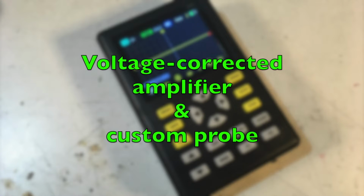Plus, you don't have the little selection reticles to go and measure the exact amplitudes and wavelengths of particular parts of the signal, which is really annoying, and that's present in a lot of these DSOs, so you don't get that here. But if I were to set this up as a fixture just for measuring noise, then I would probably build a custom voltage corrected amplifier, shooting known amplitude voltages to the front end and then readjusting, probably a JFET amplifier up at the front, or maybe feed a JFET into a MOS or an op amp, and then program the gain so that I know exactly what it's supposed to be, and then make up a custom probe and compensate for the 2-to-1 divider or whatever that would be. Because the alternative would be buying a low voltage, low noise, high precision active differential probe to put on the front end, and I'm not going to put a bajillion-dollar probe on the front end of a cheapy little oscilloscope anyway.